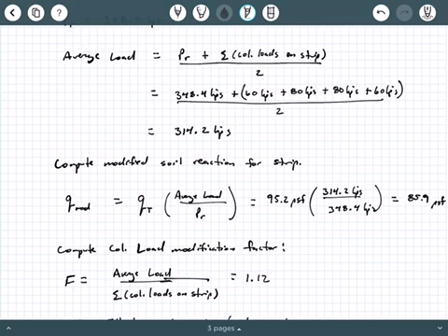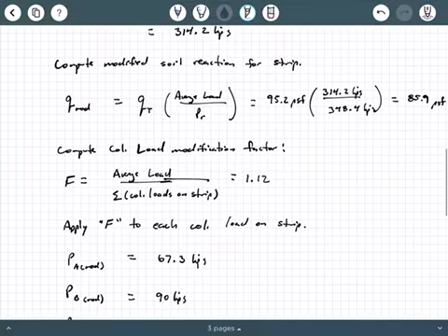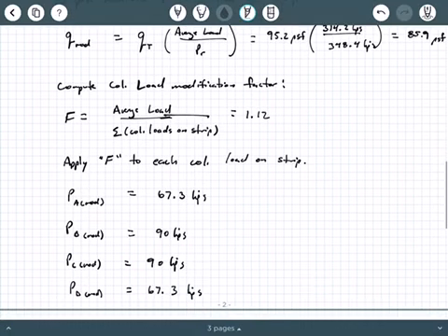So in order to have a static equivalent system where the shear diagram closes properly and then the moment diagram closes properly, you have to adjust some of these values. You're taking things that are happening on the whole slab and adjusting them for the strip of interest. So that's what these steps are doing for us.